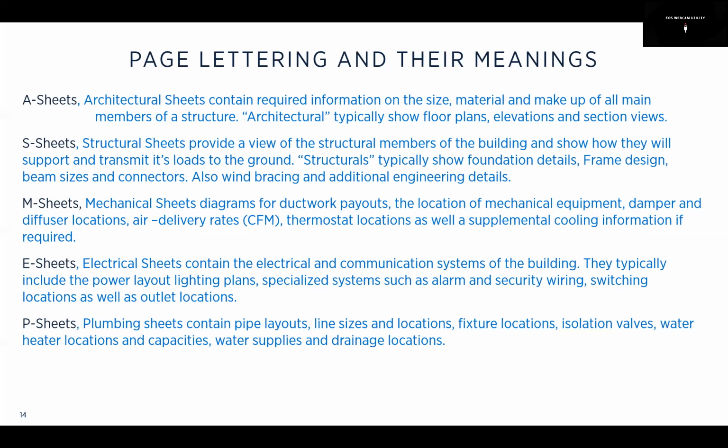The architect doesn't always know where the speaker placement is going to be, where the cable outlets are going to be, where the security systems' control boxes are going to be. So that would come as a separate supplemental drawing from your contractor. Sometimes, if it's a big commercial project, they already know where everything's going to go. It could be included. But on a smaller project, typically they're going to come out as a supplemental drawing.